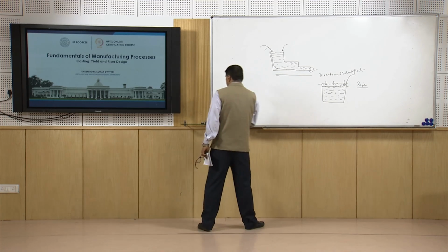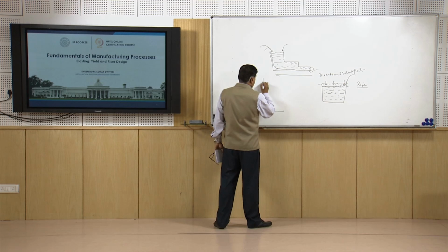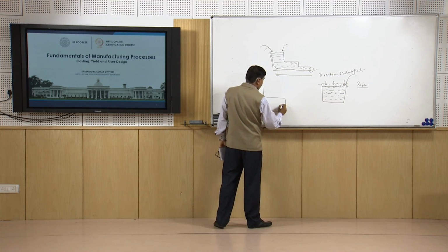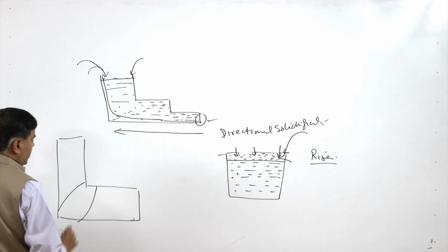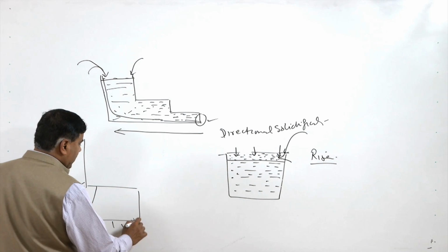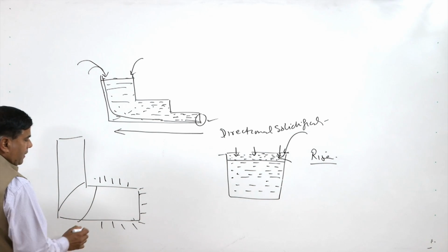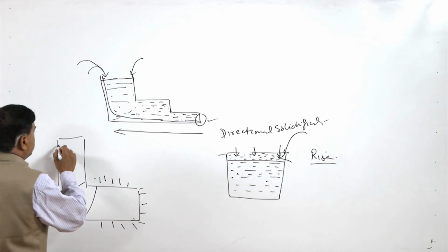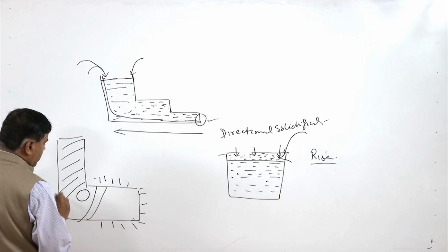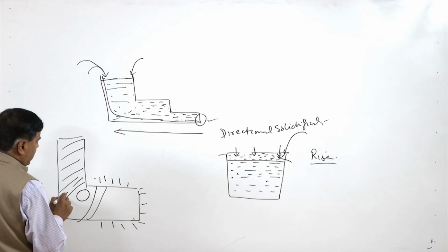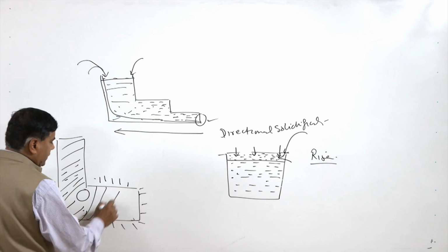Like if the mass of the casting is like this. Here, in this case, the mass of the molten metal in this zone is much more, and in other areas the heat transfer will be causing the solidification, and the solidification will of course be progressing, and at the end here we find that some porosity is left and the shrinkage cavity is left in this area of the casting.